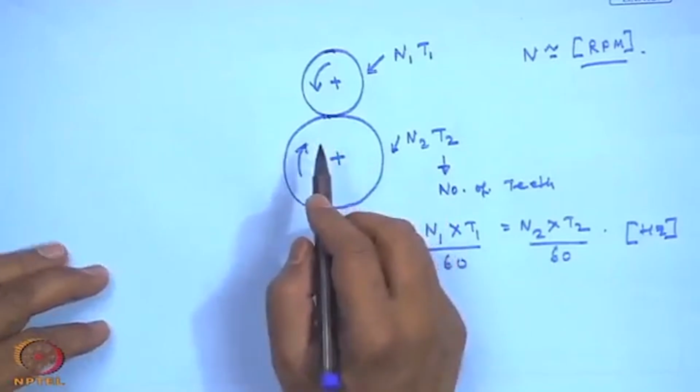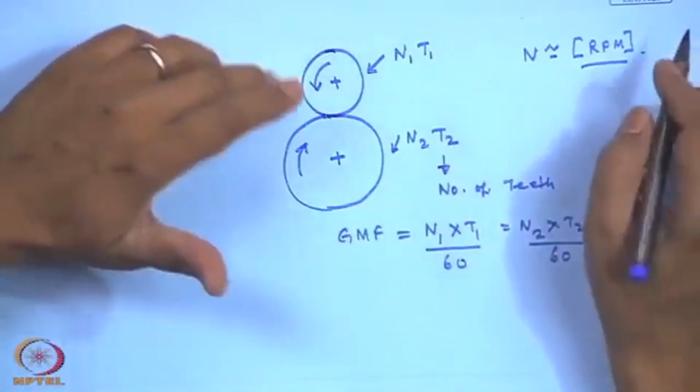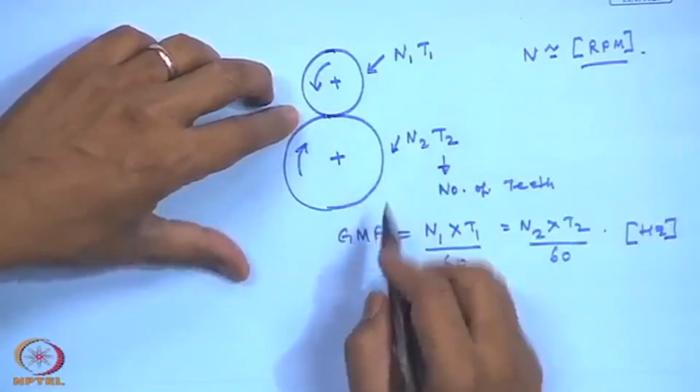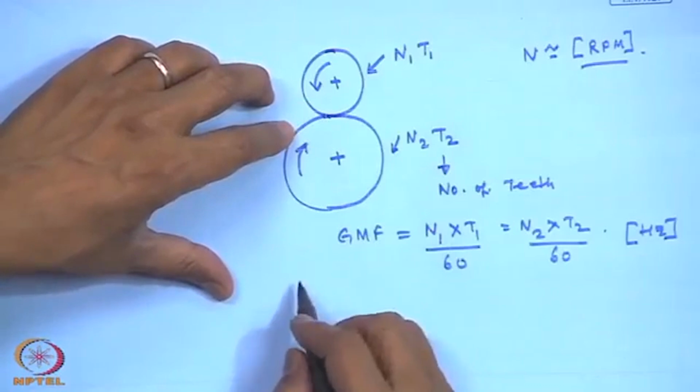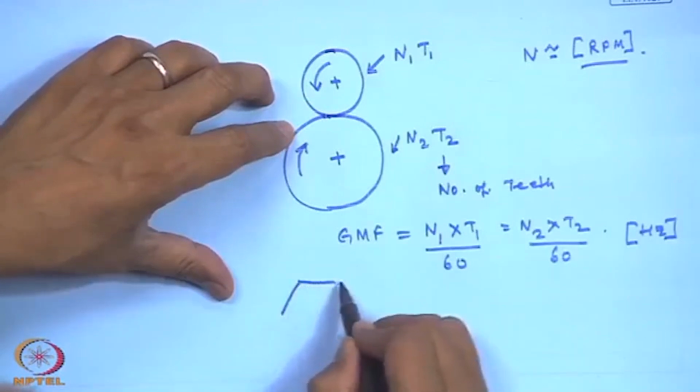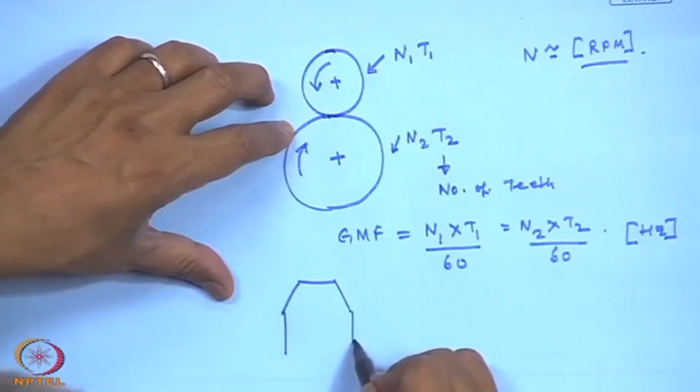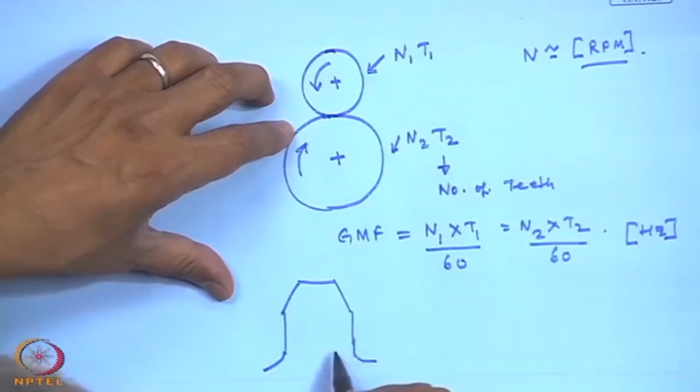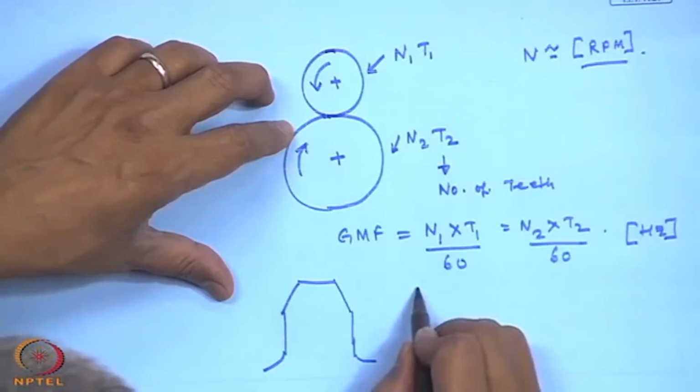So, because of excessive load, sometimes gearboxes are designed to carry a maximum load, because the famous Lewis equation is used to find out the stresses at the root of the gear.